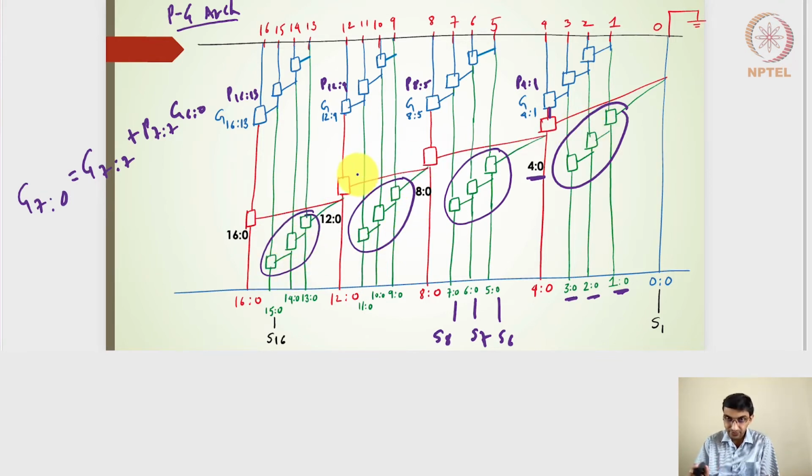Only externally, in the interaction between the four groups, does it utilize the carry look ahead adder, because here its own group generate and propagate signals are created. But internally, when it generates the 3:0, 2:0, 1:0, or 7:0, 6:0, 5:0, it actually does the carry ripple addition.